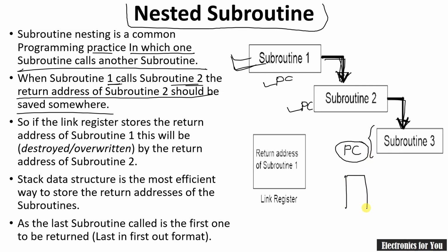this address is to be stored somewhere, and it is stored at some memory location which is indicated by the stack pointer, and this memory location is nothing but the internal memory location, and this actually follows the format of LIFO, that is last in first out. First, note that the program counter is first modified here, let the first address be 2030 here.